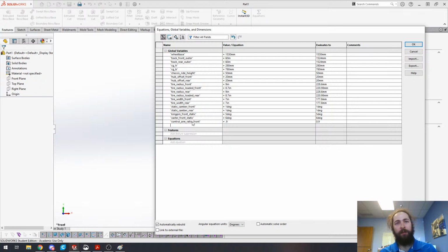And then in that case, you have at least a somewhat intuitive idea of what your camber gain is. Again, a value closer to 1 will get you less camber gain. A significantly shorter upper control arm will give you more camber gain. That's the relationship here.